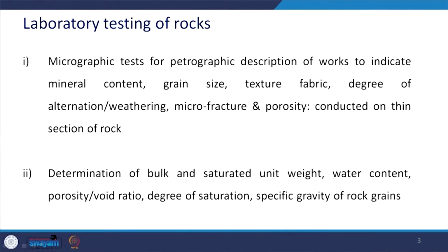So, basically the petrographic test is for petrographic description of rocks, to indicate the mineral content, grain size, texture, fabric, degree of alteration and weathering, microfracture and porosity.